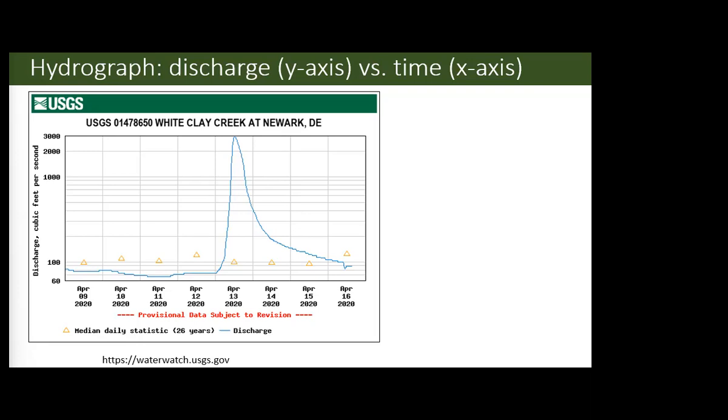So we had to find 1 million gallons of water a day in central Pennsylvania, where the Amish live. And as you can imagine, the Amish do not like when you mess with their water. So it was a very interesting project to work on. We did a lot of these types of studies where we were measuring stream influx. We were measuring what would happen if we pumped the groundwater, because as you pump the groundwater, the stream is going to start to infiltrate into the ground because you've lowered the water table. So water flows downhill. And if you've increased the gradient between the stream channel and the groundwater water table, it's going to flow downward into the water table. We're going to lessen the amount of water that comes out of that stream. So that was a really cool project to work on.